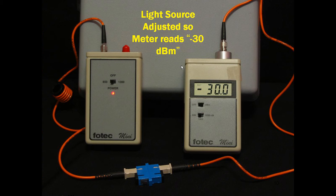But all these losses in fiber optics are standardized, and when you look at a fiber optic setup where you're going to use a transmitter and receiver, you look at the specification sheets for those products, and it's going to tell you these products can take -12, -13 dB of loss from the transmitter to the receiver. So this is how you measure that to make sure that the fiber you installed, or the fiber that you're being allowed to use by the customer, is within industry specifications, or there's not too much loss in the cable for the devices that you're going to connect.